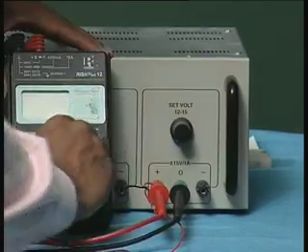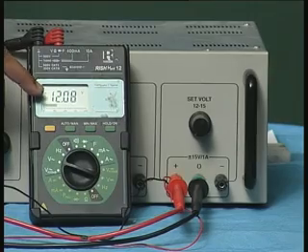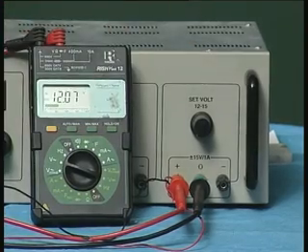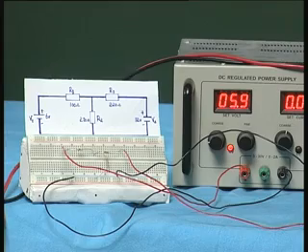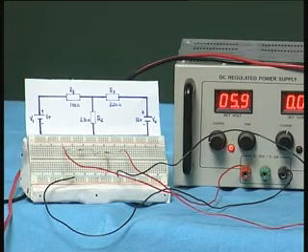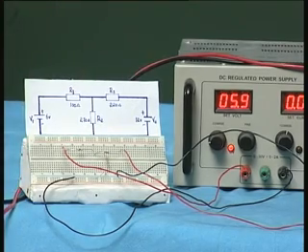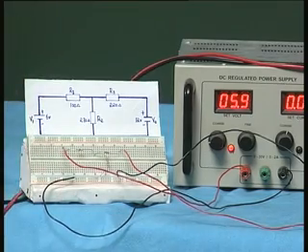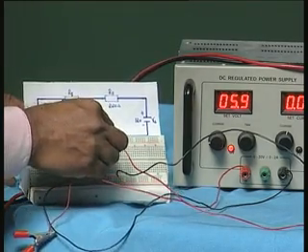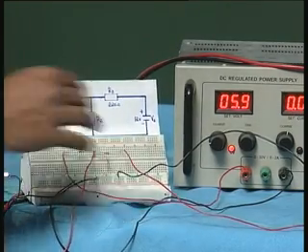Using the multimeter, I will connect it to voltage range and measure DC volts. Now you can see this is 12 volts, 12.08. So this voltage source is 12 volts on this side, and this voltage source from here is 6 volts. Now I want to measure what the voltage across R2 is. What we will do is directly measure the voltage. So I will connect the voltmeter across R2, and the other end of the voltmeter I connect to the ground. So what is the voltage I get?